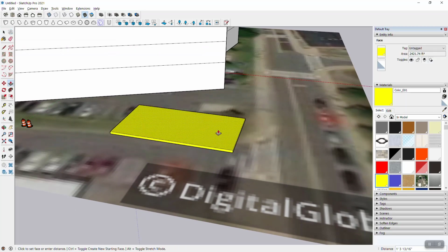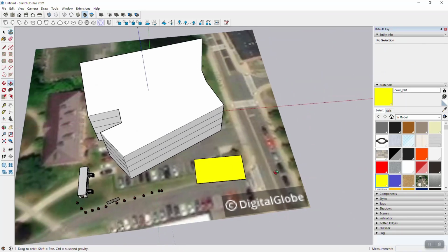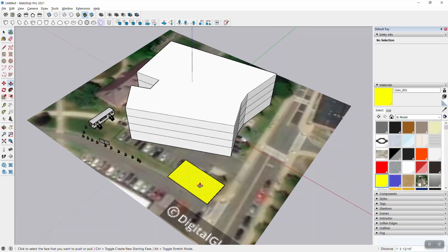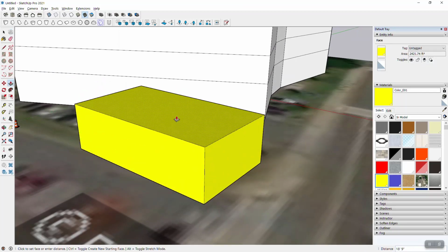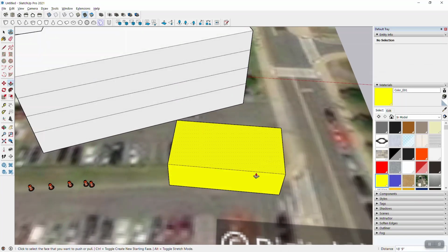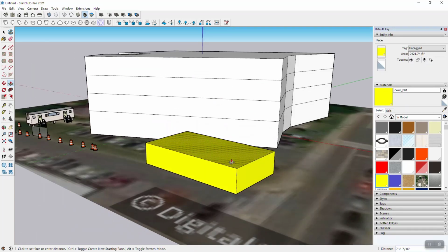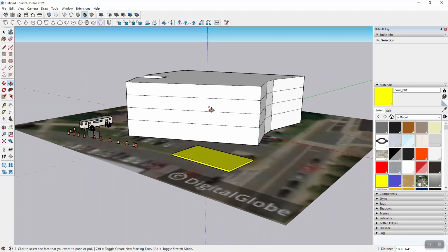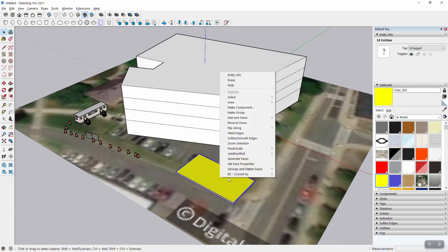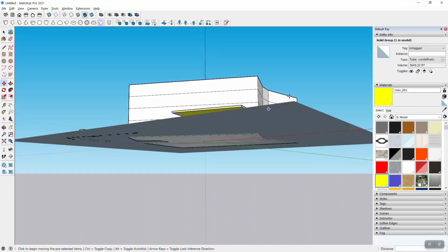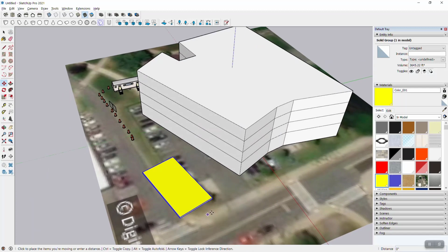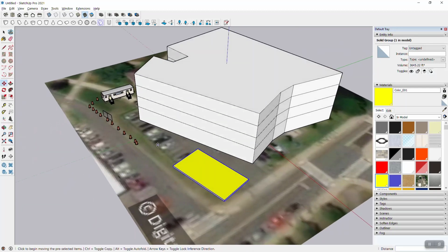One is to give it a slight thickness right there. That way it remains diagrammatic. It's just highlighting something, but you don't get Z fighting. You actually do get a little thickness. And if you need to block something out in terms of space, as in this volume here needs to be free of anything else or cranes or whatever, then of course you can use that. But for the most part, just a little thickness will do. And then of course you can triple click that, make it a group, and then you can move it, arrange it, rotate it, much easier, just like that. Oopsie, I actually moved it up. That wasn't supposed to happen. But you can move it in plane and so on, much easier.